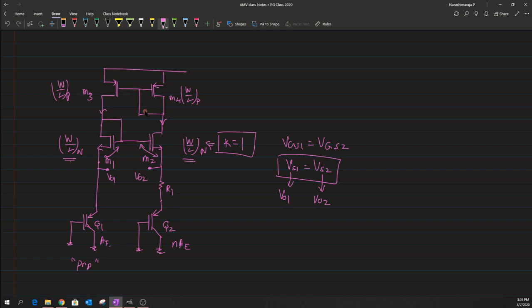Okay. The only small modification that we have done in the circuit is that rather than having this M1 and M2 as two different aspect ratios, we had ensured that both have the same value, such that our VO1 would be exactly equal to our VO2. So except for that small change, the supply independent circuit is just being placed on top of our general structure of BGR.